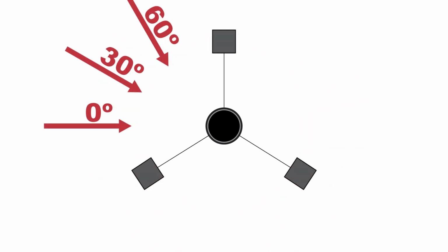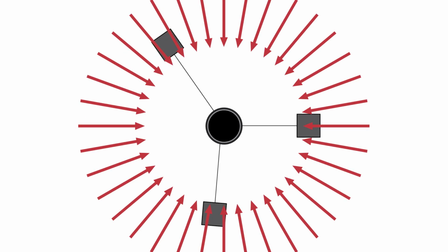When we have symmetrical deadmen, we only consider 3 different load directions. When the deadmen are not symmetrical, we have increased our load combinations by 12 times.